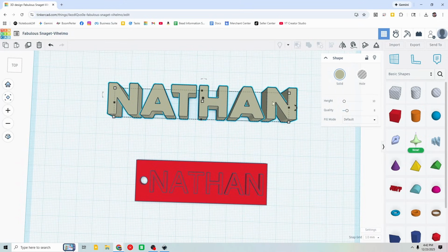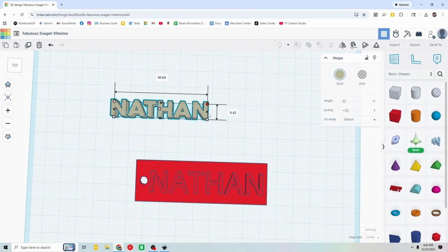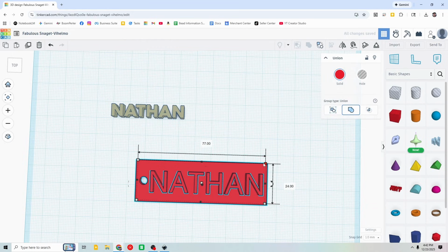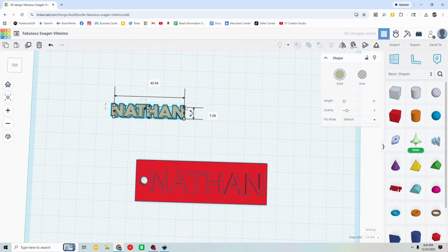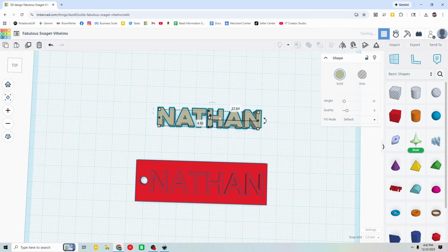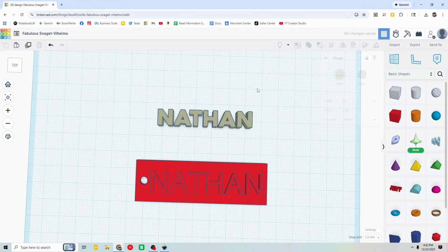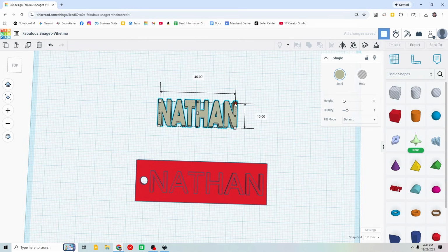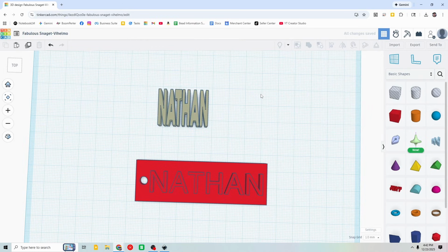Now, we made the rectangle keychains before, but it's a little bit too plain. And mine ended up being a little bit large. So I'm going to change that up. I'm going to make this about, let's go 55. Now, what am I doing here? You can click and drag these handles, but again, you're going to ruin the aspect. It's going to distort.